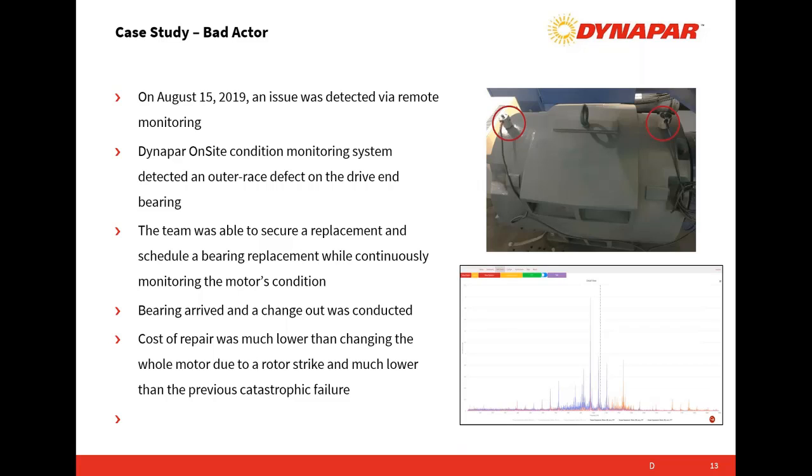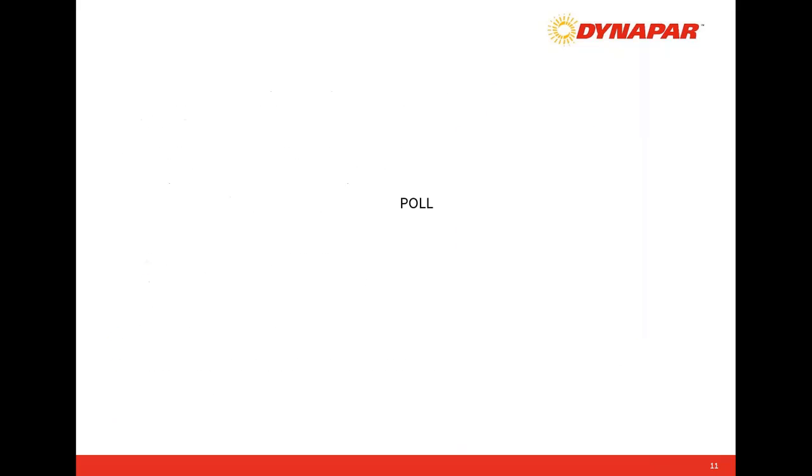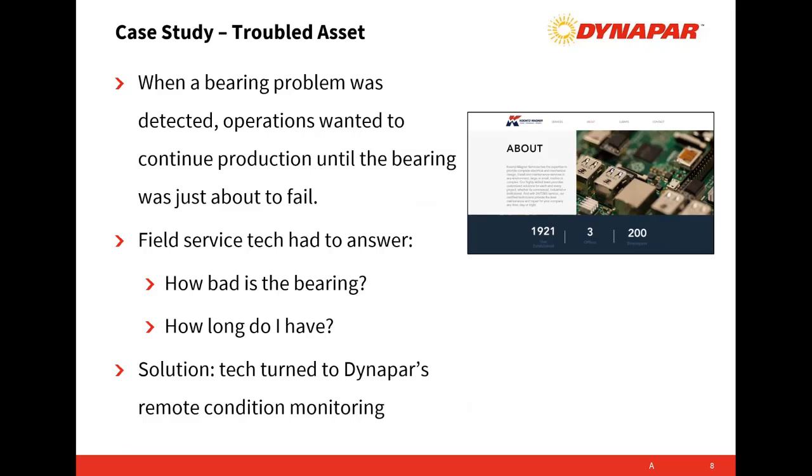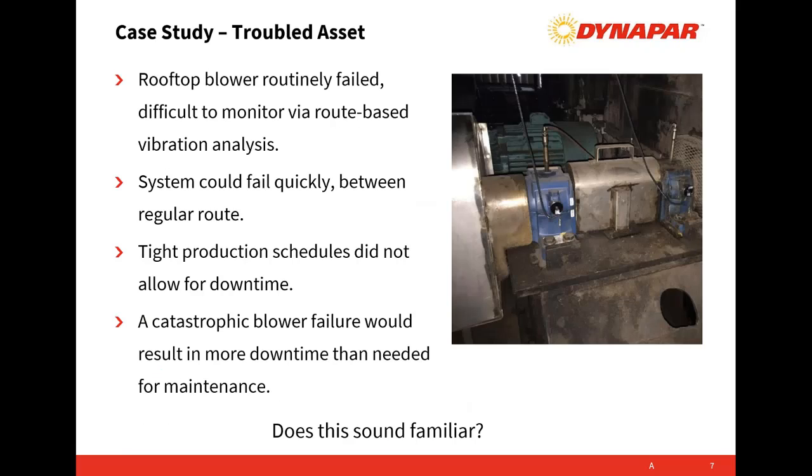So with having the ability to take triaxial readings, we can place them in the axial direction, which is perpendicular to the shaft, and which gives us direction. However, it does not matter how we mount them, as long as we know what direction the sensor is, and we can still determine what kind of anomalies are occurring. So they're pretty simple mounts.